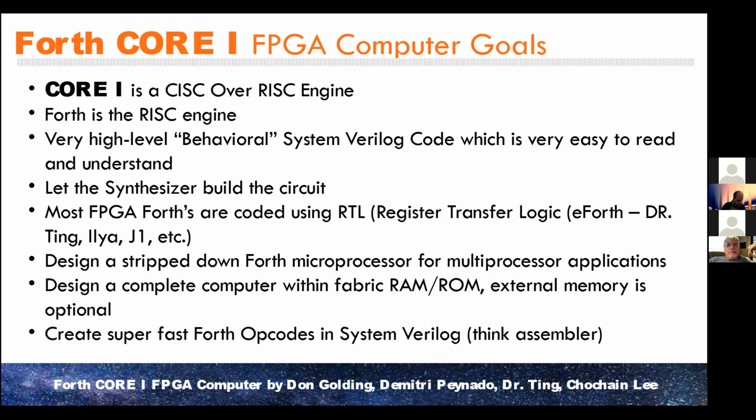One of the other things about it is when you define your own word, you can make that word an opcode. The other benefit of the way we're doing it is there isn't a timing issue where you have to keep the opcodes very primitive because an opcode has to finish in, for example, 50 nanoseconds.